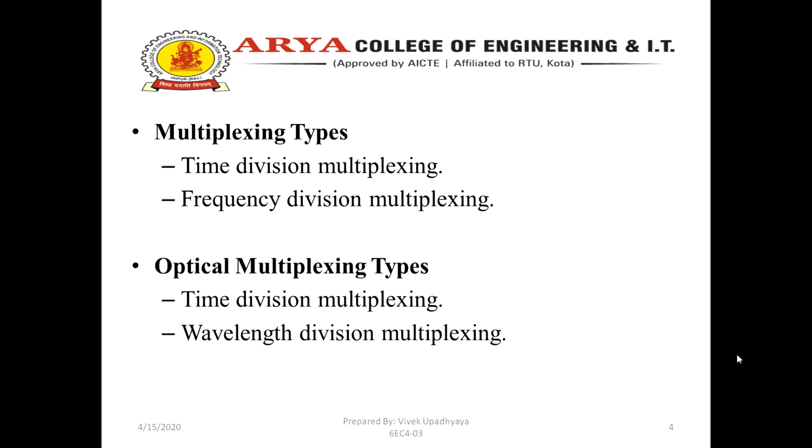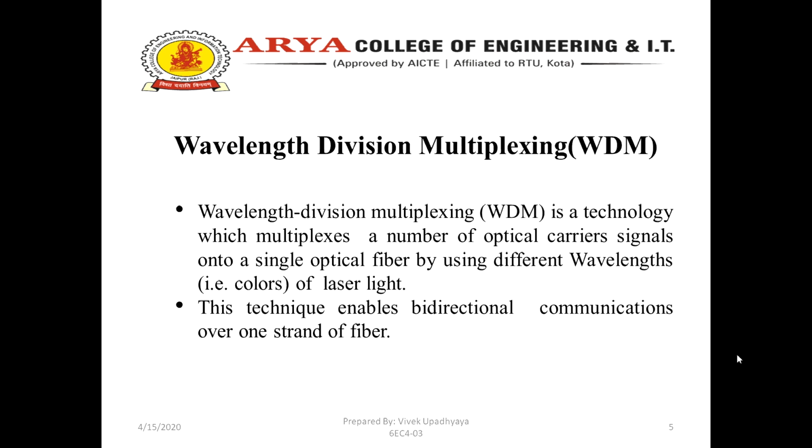For multi-channel operation, therefore, it is possible to operate each source at a different peak emission wavelength and achieve simultaneous transmission of all the optical signals over the same single fiber. Now, these are the basic concepts involved in the WDM.